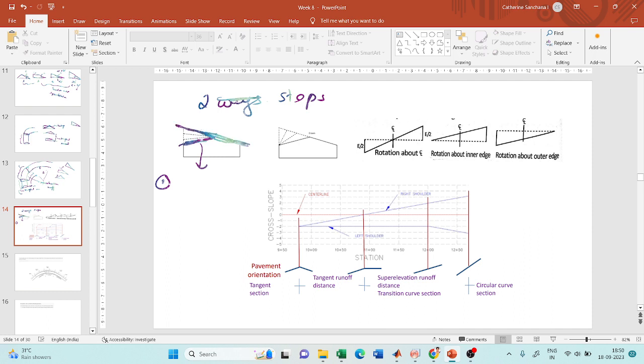I can do it in two ways. If I have a camber like this, I can increase it like this. First, increase some height here, then again increase some height, then again increase some height and bring it in par with this slope. This is one method of doing it. So this is the first step. First step is removing the reverse camber and making the slope equal to the slope of the camber.